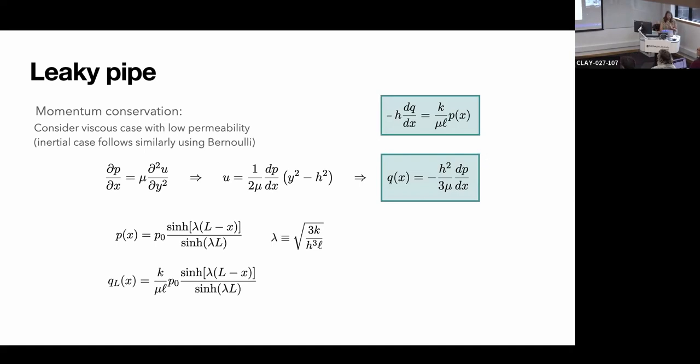And the last piece I need was the thing that I highlighted, which is that I put this K, this permeability, in as a placeholder, saying, okay, there's some parameter that tells me how hard I have to push on my fluid to get it across this membrane. But that's going to depend on the geometry of my little plates, right? So now I want to relate K to the geometry of my little plates. Okay, I have one more slide of math, and then I'm going to throw my microphone off my face, and then I'm going to show you some results.